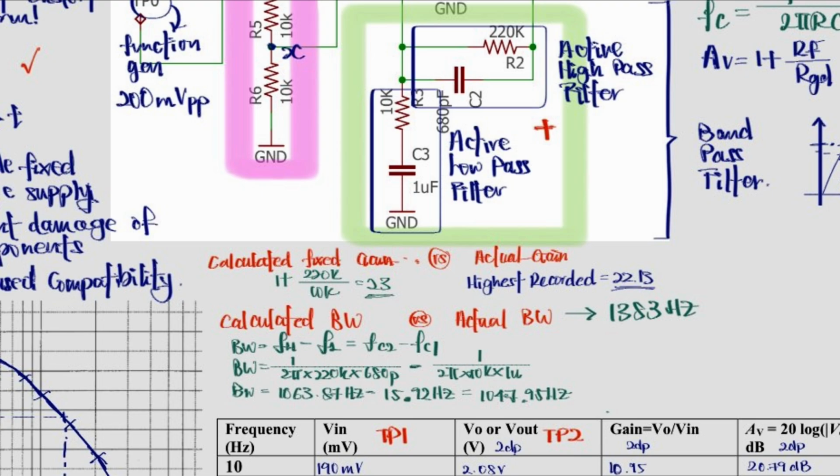This range of frequency is chosen because normal heart sounds are between 20 to 150 Hz and murmurs can go up to 1000 Hz. So by using the bandwidth estimated at 1383 Hz, we capture all important heart sounds while filtering out unwanted low and high frequency noise.